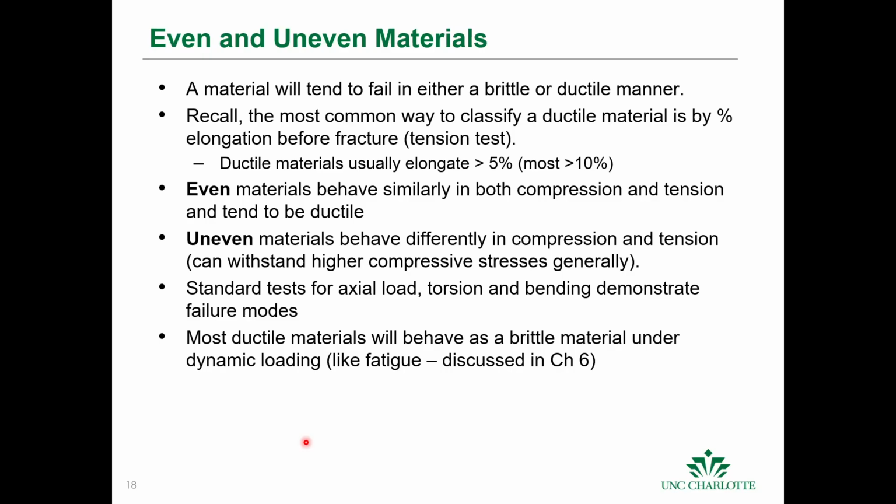Now, when we talk about materials, one way to look at them is as even and uneven materials. Materials will typically fail either in a brittle or ductile manner, but even ductile materials subjected to fatigue loading can fail in a brittle manner, and we'll talk a lot more about that throughout the semester. But even materials behave similarly in both compression and tension. Typically, they tend to be ductile if they're even materials.